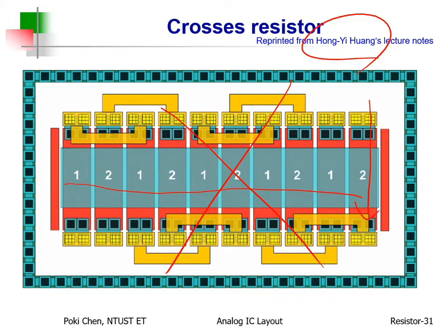According to this kind of noisy device, you had better use such kind of guard ring, okay, to limit the noise it generated. However, the noise can run not only in all those four directions, but it can also go up or go down, right?